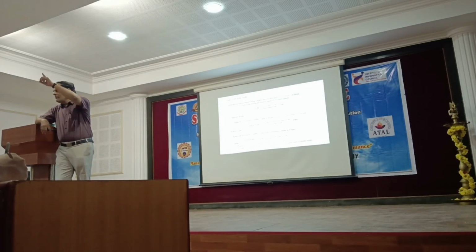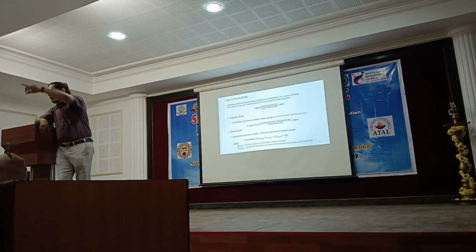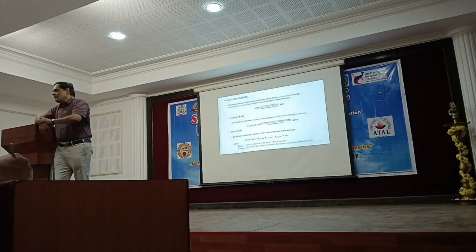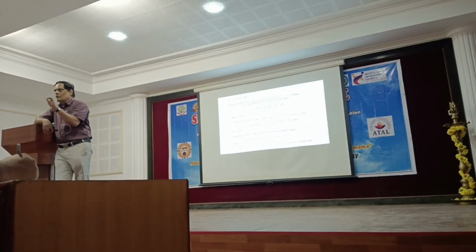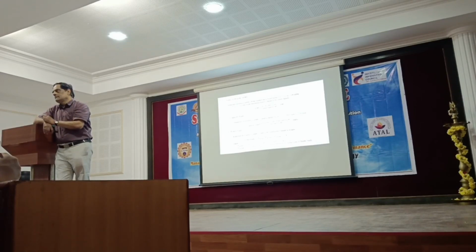Again, connected to this, we always talk about quick charging. Suddenly you are applying the brake, you draw a huge amount of power. That is what you heard of as a random load. It's called stochastic load. We are not uniformly discharging. Okay, this is called stochastic load, random load. Due to random load, what will happen? Battery will undergo quick aging. You are applying the brake frequently. That will affect the health of the battery pack.